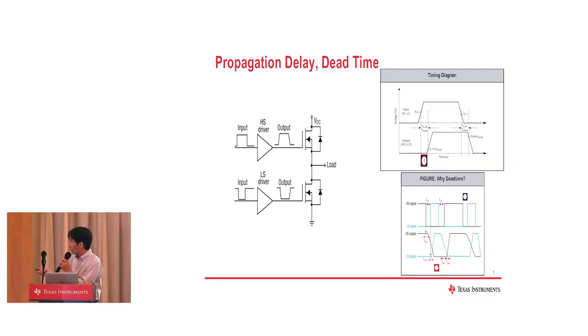Also, one of the features of the gate driver is the dead time. Dead time is the time interval in which both the input signals stay at low state. The purpose of this dead time insertion is to prevent cross conduction between the high side and low side switches, which causes a short circuit and also a lot of power loss.